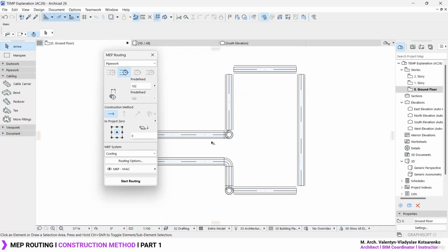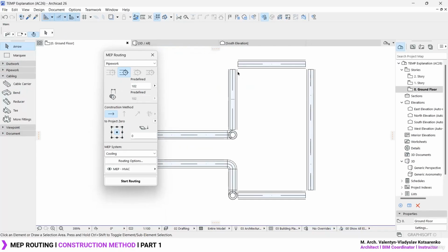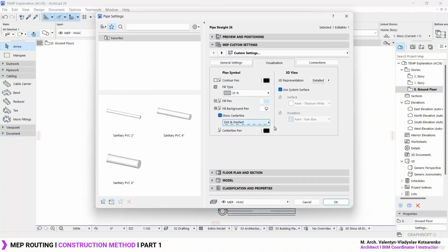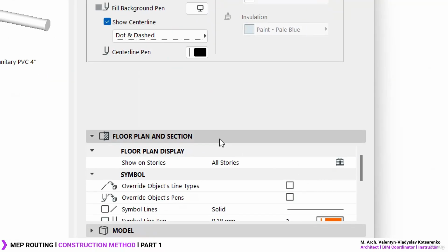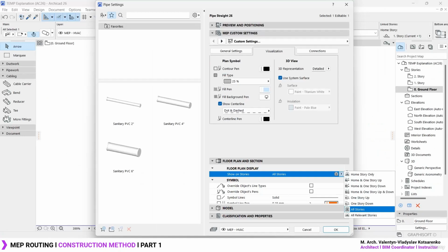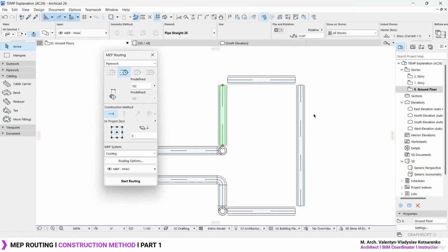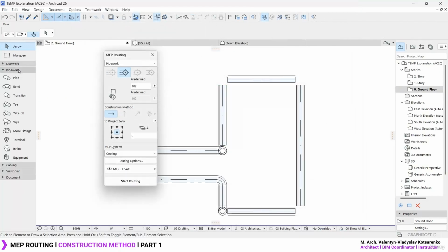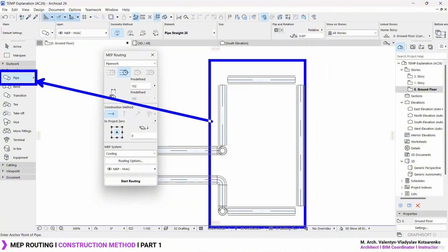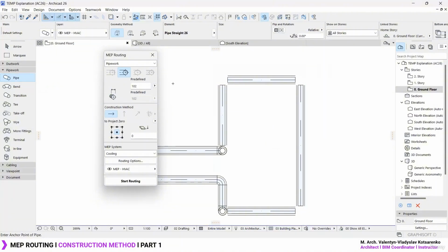And over here you will notice how everything's been documented in an interesting way, because if I remember well, before we even started generating the routine, I think I misplaced the parameter and I left this parameter unattended, so it documents in all stories. So yeah, that's one thing to keep in mind. Whichever parameter you have currently set for your pipe tool, it will be completely translated into the general elements you create with the map routine.